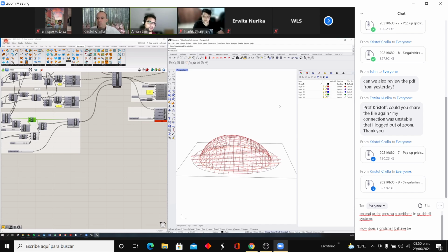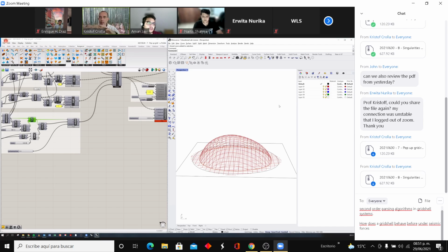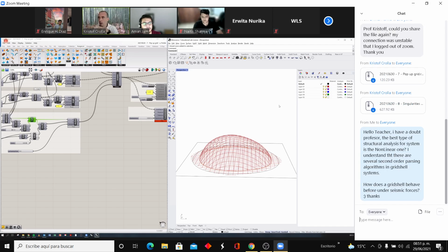Yes. So none of the structures that you have already shown us in the presentation, that have already been constructed, had unequal distant grids towards the end of the structure, like when it was deformed? Yes, exactly. Well, no, I showed two types. The ZB bamboo pavilion, like this one here, was entirely non-equidistant, because that was done one stick at a time. That's a layer method. That's different. The Fraiotto pavilion and the smaller bamboo bubble that we made with that were fully equidistant. So there's no sliding there during the construction. And theoretically, in reality, the two poles can still roll a little bit over each other. So there's always a little bit of flex that you need.